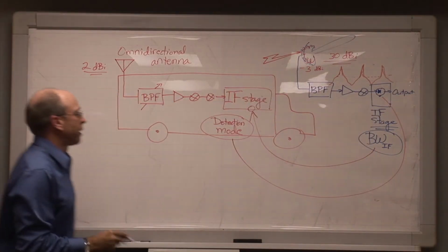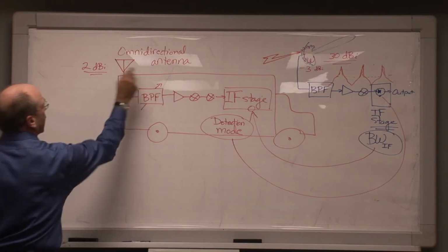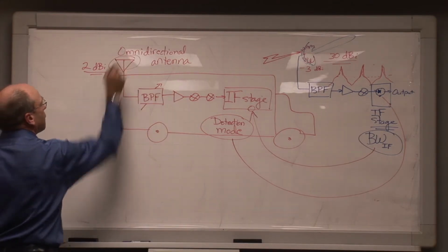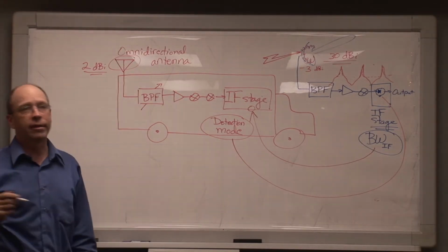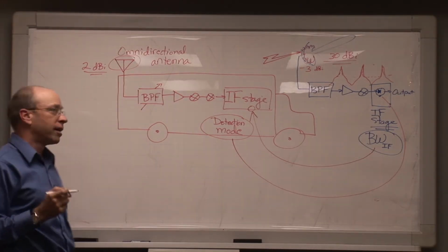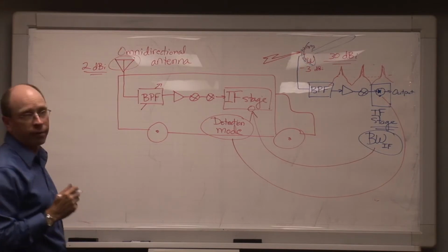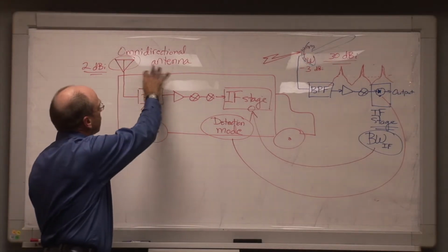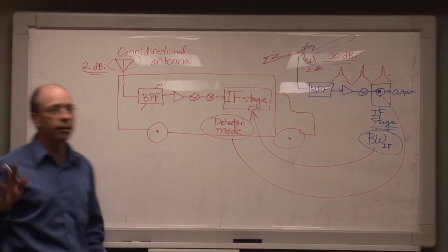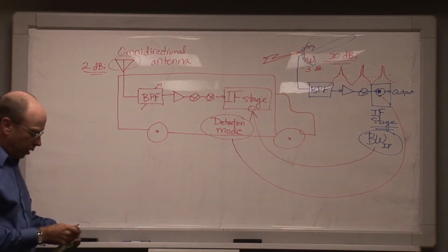So we try to replicate bandwidth and detection, but we'll typically want to use some kind of omni antenna unless we've got an extremely good idea of the direction where we think the interference might be originating. Now, if we know for sure, for example, before we arrive at the site that we've correlated the interference to a particular source, obviously we're not going to need to search around, but I'm assuming here that we don't know. We don't know where it's coming from.